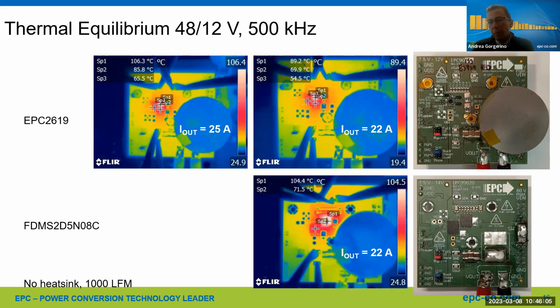But you do have to be careful about the gate driver. I think it's not about the gate charge. The main difference is the voltage rating, right? So that is definitely something to be careful with. The GaN devices, and they're all pretty much similar in the industry, are rated to a max of 6 volts, and you need to run them at 5 volts roughly.